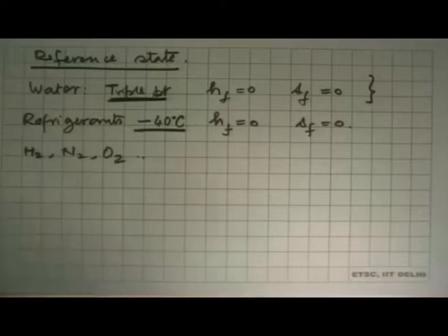Okay, here is the question. Please tell us why it is called compressed liquid. I just mentioned that it's called compressed liquid because the pressure at which the water is, is more than the saturation pressure at that temperature. So we say it is compressed. It has been compressed into a liquid phase. That is the reason.